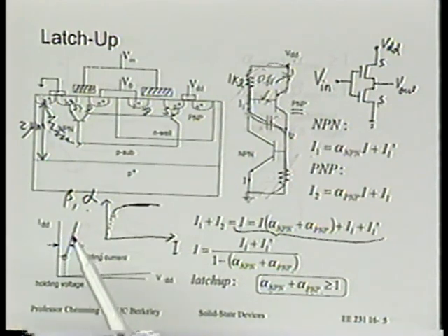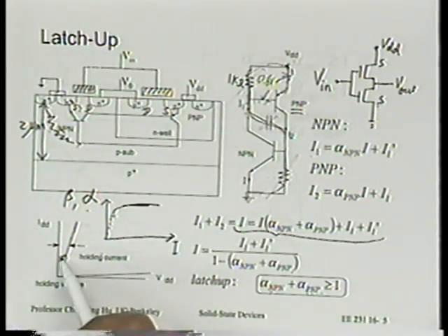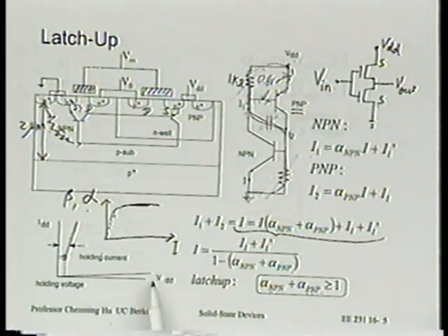Is that right? So it has been the holy grail for a long time for technology designers to design the CMOS technology so that the holding voltage is actually larger than VCC or VDD. Right? If that's the case, you don't have to worry about any trigger or anything. If VDD is smaller than the holding voltage, that would be the best, the surest way of stopping latch-up.